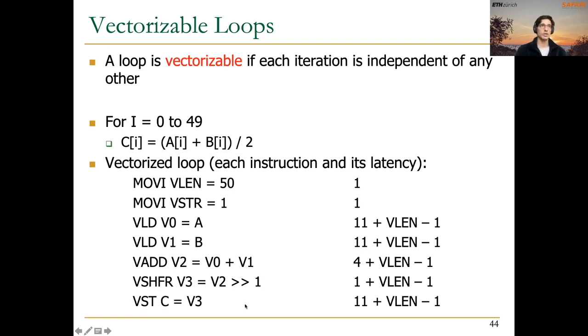And now if we think about the latency of each of these operations, except the first 2 that are simpler operations, where we just write a single value onto a single register, so they take only 1 cycle, the rest of them can be pipelined in some way. And that means that we can make them more efficient and more productive, and we will get higher throughput.